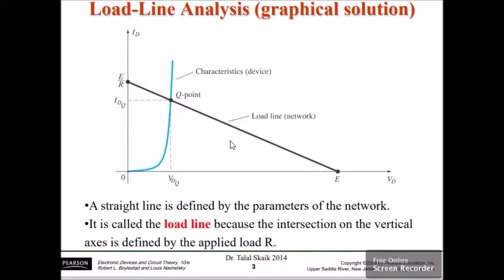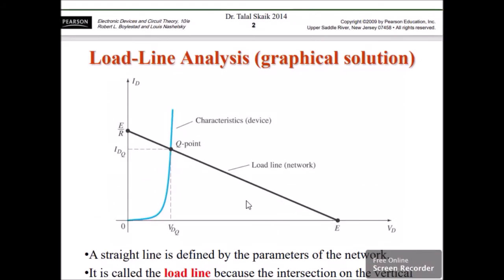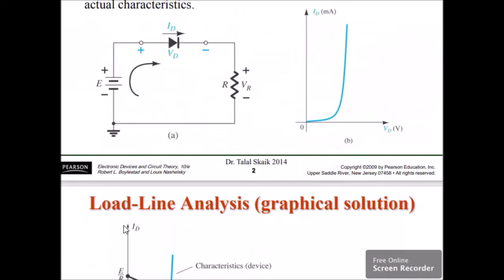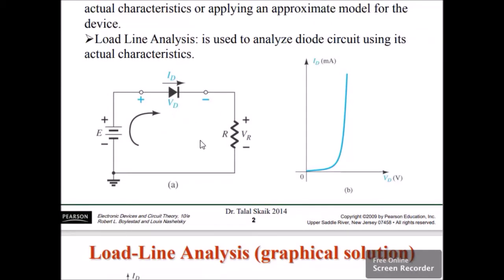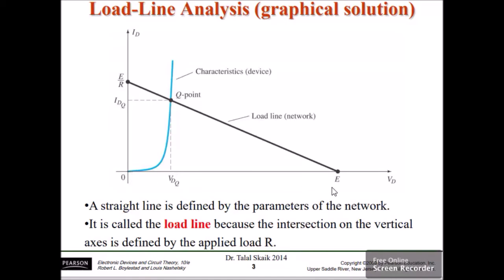Alright? Now, going back to the load line analysis, kailangan natin itong dalawang point. Okay, we have to determine this point so that we can draw a line so that we can approximate saan banda yung kanyang Q point. Alright? Now, question. We need this line. Saan ba to? If you try to relate it back to our diode, anong value ng ating current dito? ID. Alright, so yung ID natin at this time, dito, is 0. So, ibig sabihin, we will try to analyze this circuit using ID is equal to 0. So, if ID is equal to 0, you get the corresponding value of your VD.